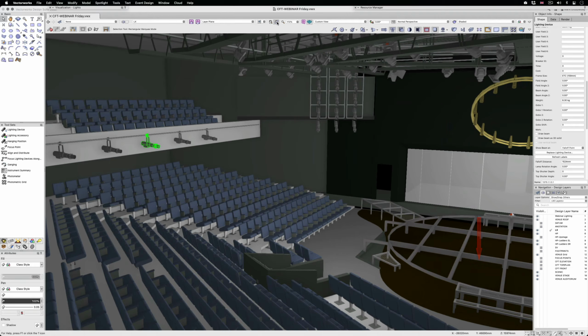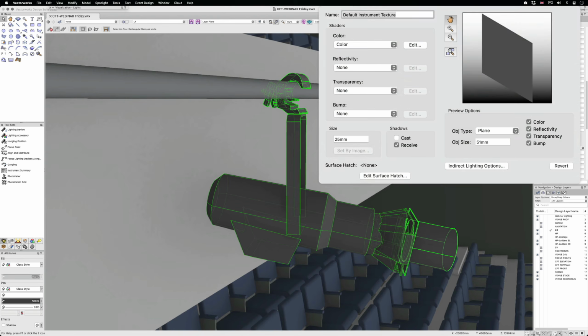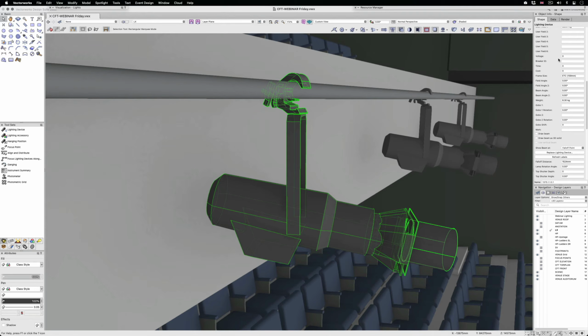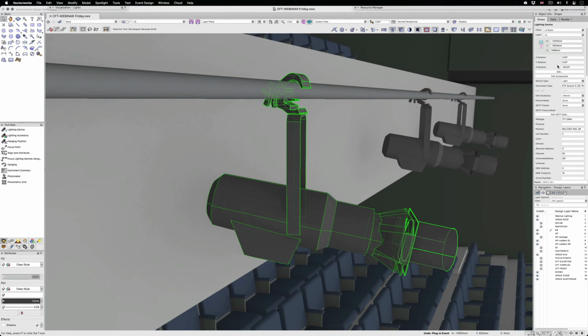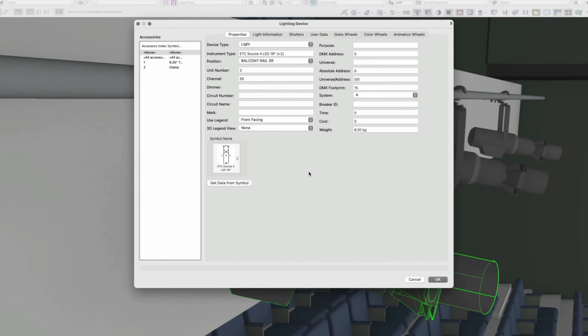Currently, caustics are not engineered to travel through objects with the default RenderWorks texture that is used for lighting devices. This is because the caustics don't understand the cast shadows nature of the RenderWorks texture. So you need to place a symbol that has no geometry between it and the light source. For this reason, I have a substitute symbol that has virtually no geometry at all.